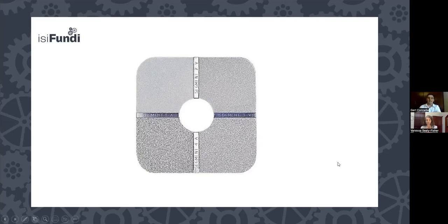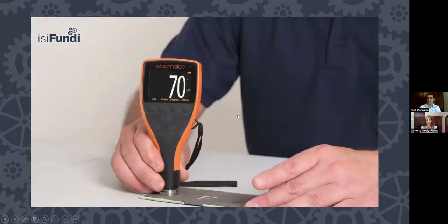Now, this is ASTM method A, and this is the most preferred method and less intrusive method of actually measuring the surface. But again, it's only a visual representation. The next one that you see is the most common one used in the industry, if you are allowed to use a gauge that is now not intrinsically safe, I can put it that way. So obviously the comparator used earlier, if you're in an area that you have to use an intrinsically safe instrument, that's the preferred method for measurement. And even if it's a curved surface, you can use a comparator for that.